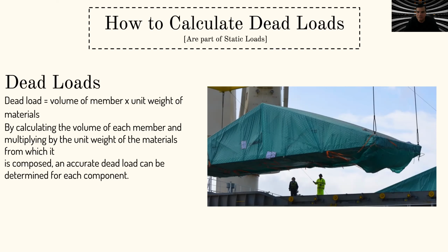We will calculate the volume and we will multiply by the weight of that material. And the same with everything. From the windows, from the doors, everything will be together, and we will put all those forces, all those weights together, and we'll have the weight of everything that composes the building that is fixed.